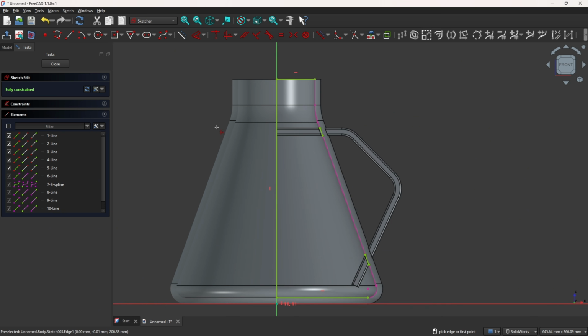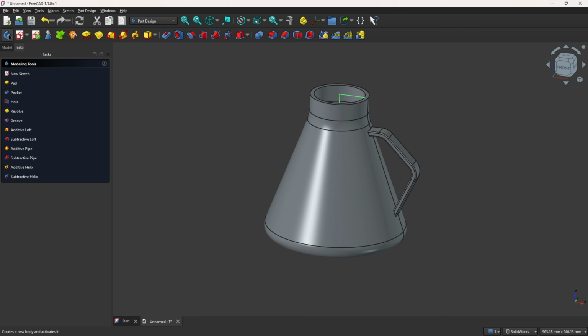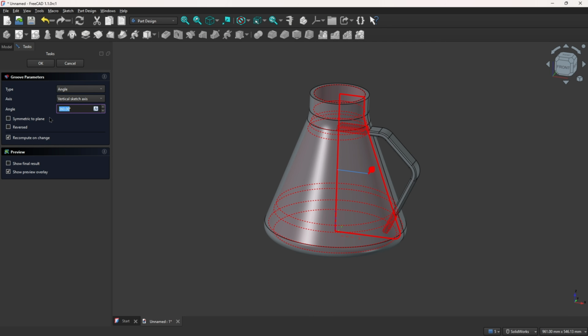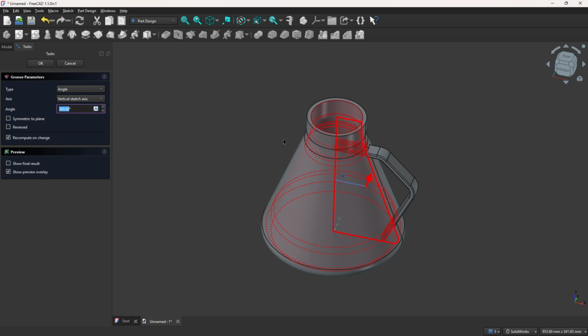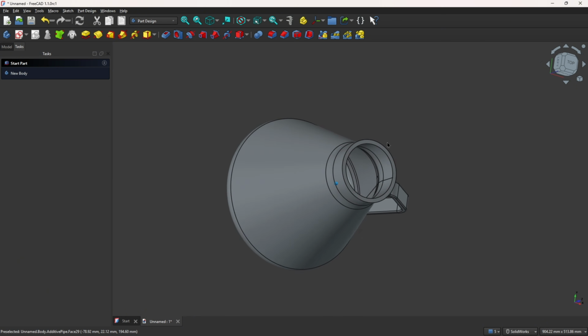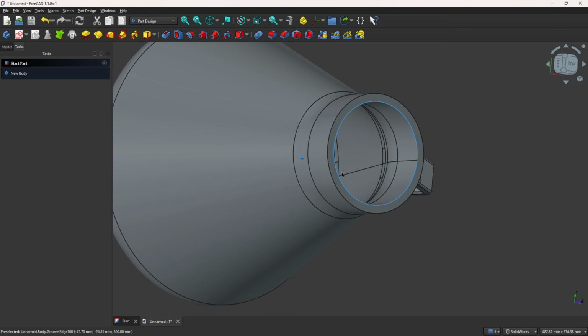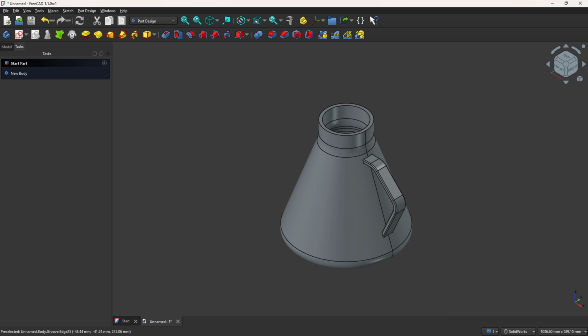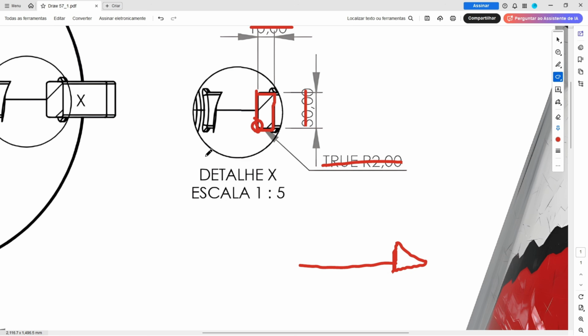We made this profile. Now leave the sketch and go to Revolve. But here is, sorry, it's not Revolve, it is Groove. The angle here, 360. We will cut here inside and press OK. Look inside, we removed these two parts.